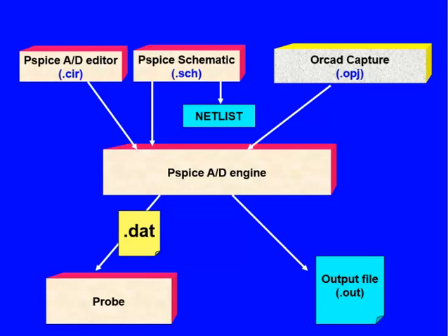In lecture 1, we already discussed the PC version of the SPICE model. In the PC version of the SPICE model, we can describe the circuit using programs, and these programs are saved as a file with the extension .cir, or we can draw our circuit in a workspace as a schematic diagram, which is saved with the extension .sch.